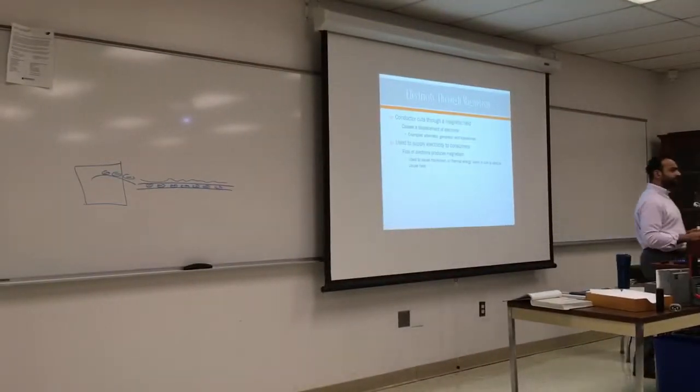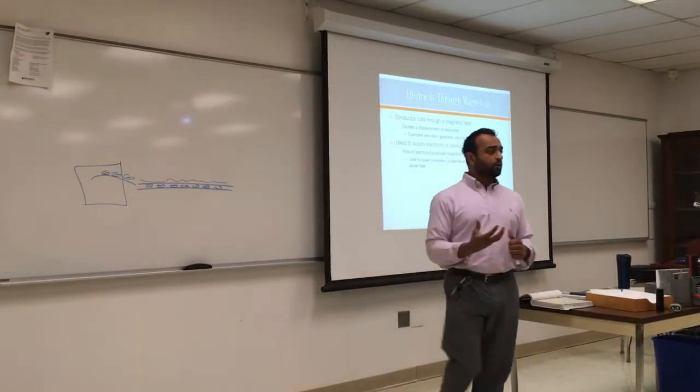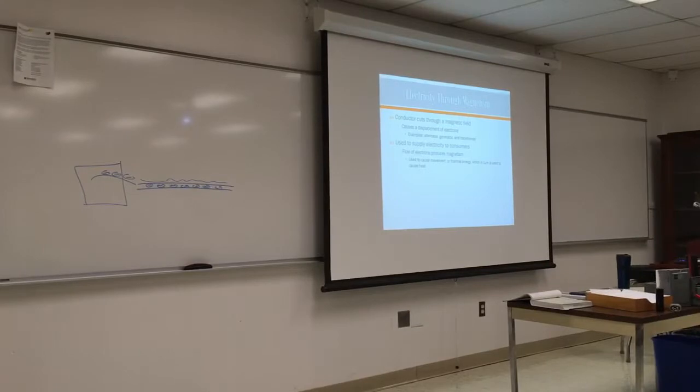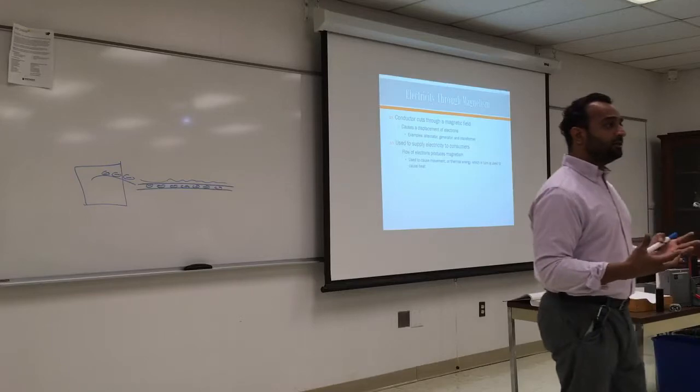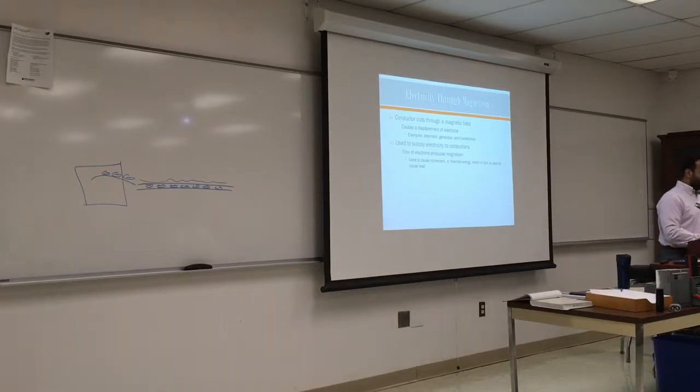Yeah? What's a transformer? Good question. A transformer is a small device that changes power based on induction, and we'll talk about that in a whole chapter. You know, we used to play video games and you have a big box, you plug it into the wall, another wire comes out of it. A transformer changes electricity from either higher to lower, or lower to higher, based on winding. If you ever open a transformer, what do you see inside? Coil. You'll see a coil, and I'll show pictures. So there's a coil, and there's an iron core, and it works with induction, and we'll talk about it as well.